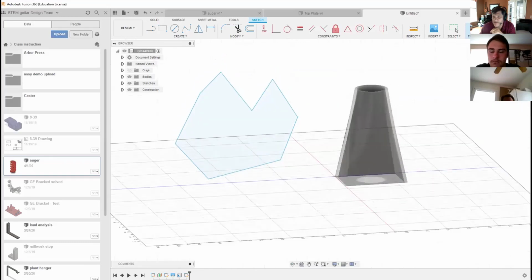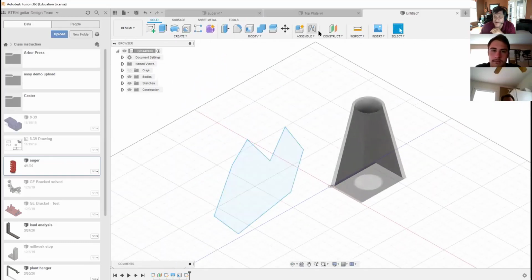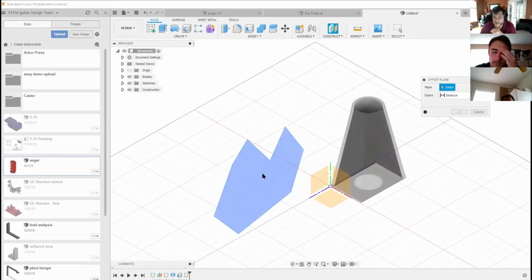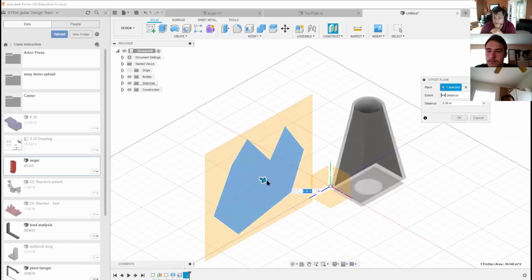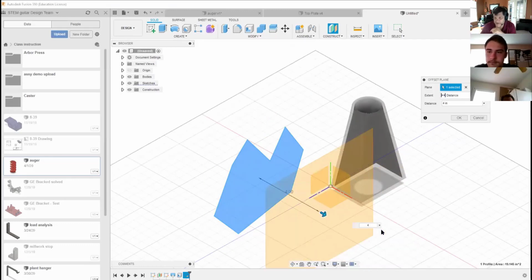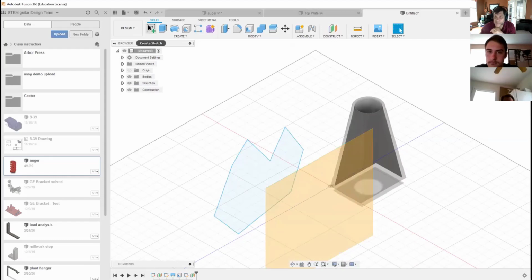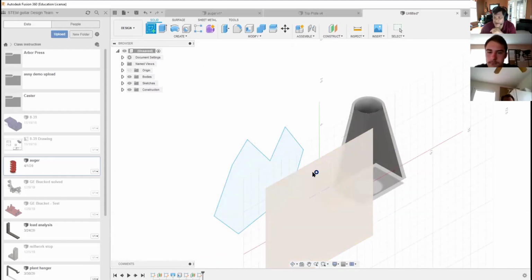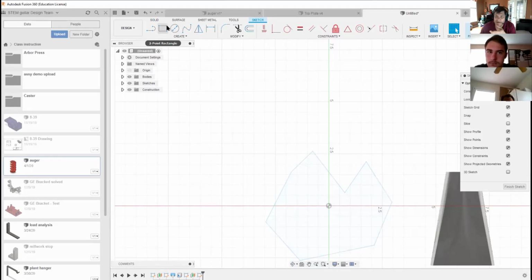Okay, that's going to be a unique shape. And then I can say, from this shape, I want to create another work plane. I don't think I'm going to go 6 inches, but we'll go 4 inches off. And then I can produce a new sketch on that work plane. And then we can create another object.